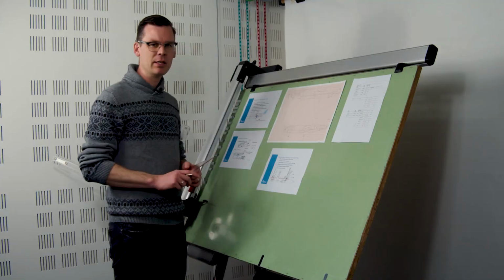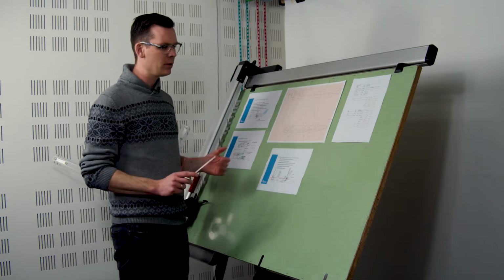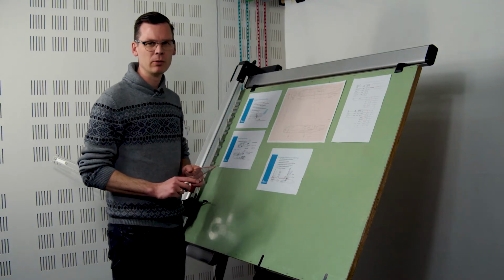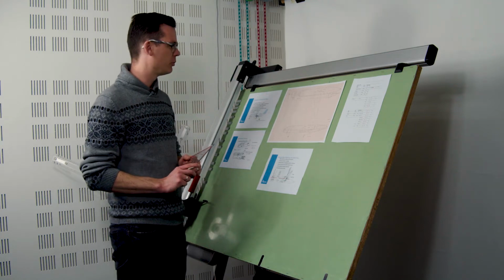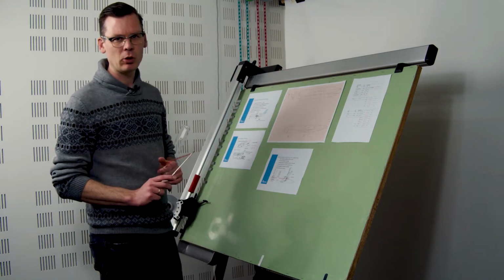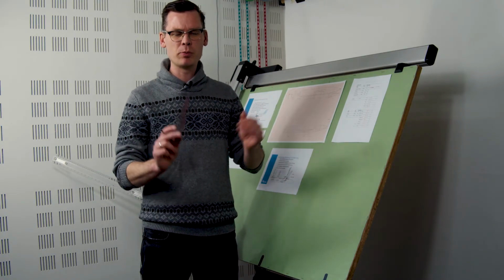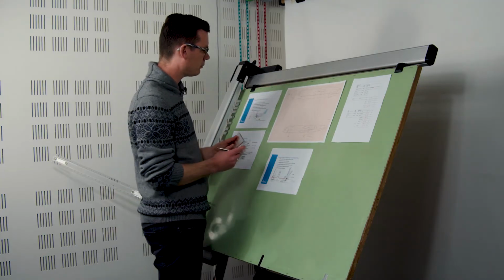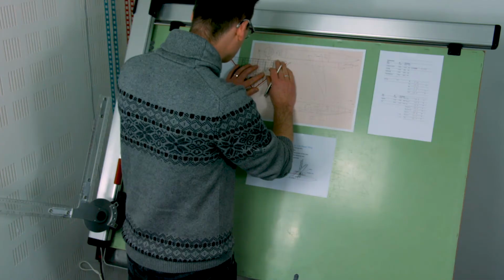The lateral tip over criterion is typically dictated by a certain angle, psi, and you can find in the slides actually how psi is exactly defined. And with a formula, you can then compute for that lateral tip over angle what the lateral position of the wheels needs to be. And I already did that. I computed that, and it turns out the lateral position of the main landing gear strut needs to be at least 3.1 meters away from the symmetry plane. So that is actually what's going to be sizing the position.